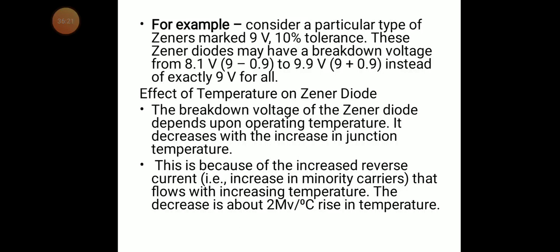Why? Because as temperature increases, the free charge carriers, minority or majority, increase, so that it may reduce the Zener voltage value.